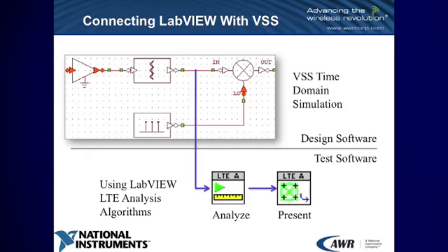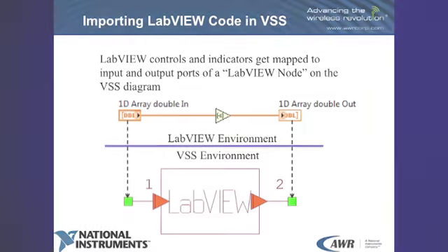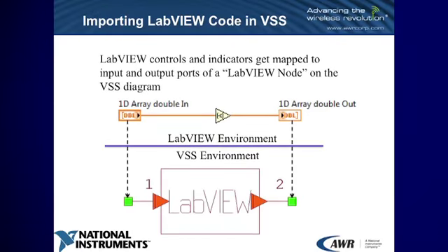The way the LabVIEW element would connect to this is merely to take the I and Q data and pass it into the same analysis blocks that you would use with hardware. Mechanically, in LabVIEW you have this notion of controls and indicators, which are sinks and sources to pass data around. These can be called from other programming environments as a subroutine. So you can imagine you have LabVIEW code, you compile it as a DLL. That DLL has a header file, which has a series of inputs and outputs that you can control from another programming environment. You can also think about that in LabVIEW.